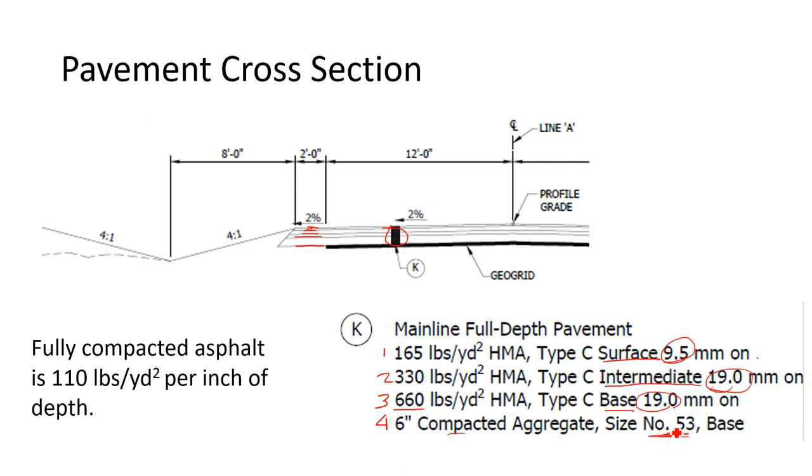And so this is, I guess you would call it, a well-graded mix, right? If you remember from soils class, it has a range of sizes. I think it tops out at half or 1/4 inch, 3/4 inch, something like that, and drops down. Doesn't have very many fines. It does have some down to the 200 sieve, but it doesn't have any of the clay-size particles and fines. So it's fairly well draining, but it also works good as a base because with all that range of sizes in it, with that being well graded, you can compact it pretty well.